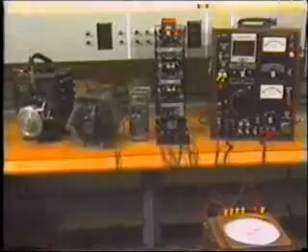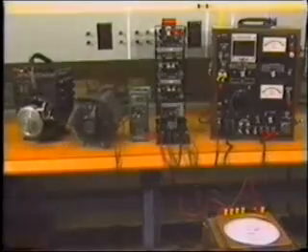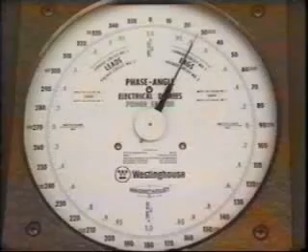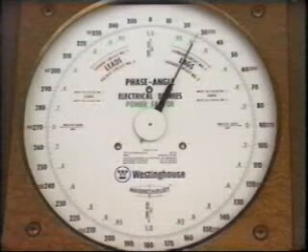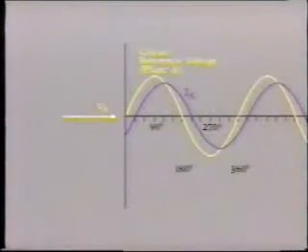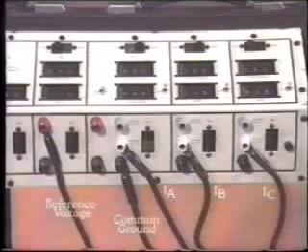Now, using the correct test plugs, current IA is connected to the circuit number 2 on the instrument. The phase angle is measured and shown as plus 333 degrees. So the current IA can be plotted like this on our phasor diagram. You can see that the phase angle between current and voltage is actually 27 degrees lag.